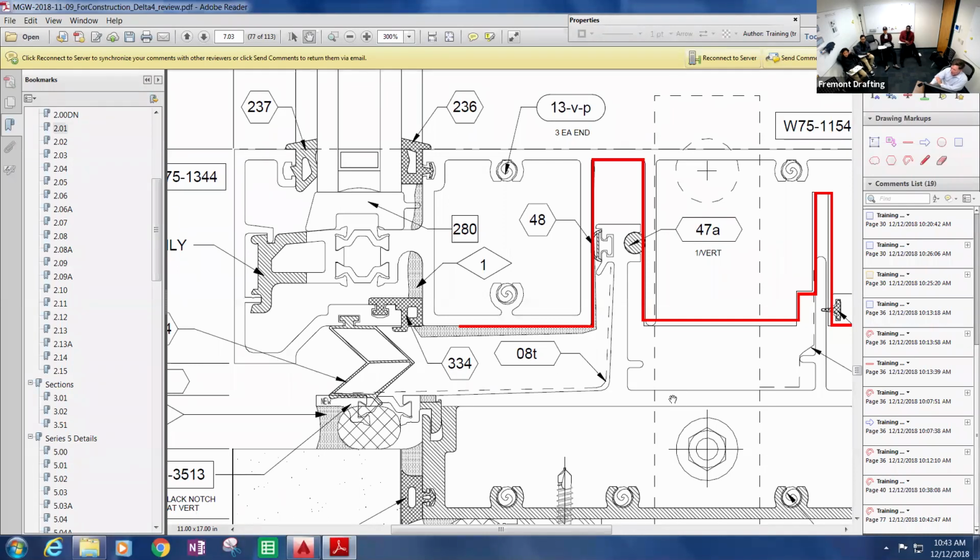If it's a 1/2 inch live load, it's only an 1/8 more. But I need that 1/8 of an inch here, otherwise the bottom of the notch will hit. And I need an 1/8 of an inch here. So it's really that I need 3/8 of an inch to accommodate it. And then if it goes to 5/8, I add another 1/8, 3 times.